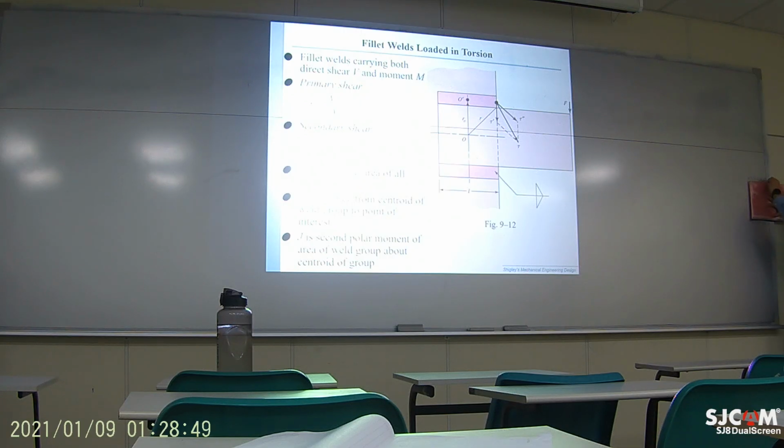By the forces and the stress inside the weld material. So it's actually these two strips of weld material that are carrying, having a reaction to counterbalance the moment generated by the external force. So that's what this figure is about.